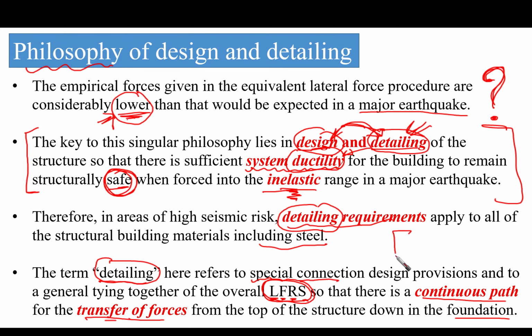Do you know that whenever we have a building and forces coming into it, we want to be sure that there is a continuous path, so that the lateral resisting system safely transfers it to the ground? If there is no discontinuity, then we are not going to face any failure mechanism. That's the point here. So detailing is securing the continuity and the transfer of forces to the foundation through our system, through the LFRS.